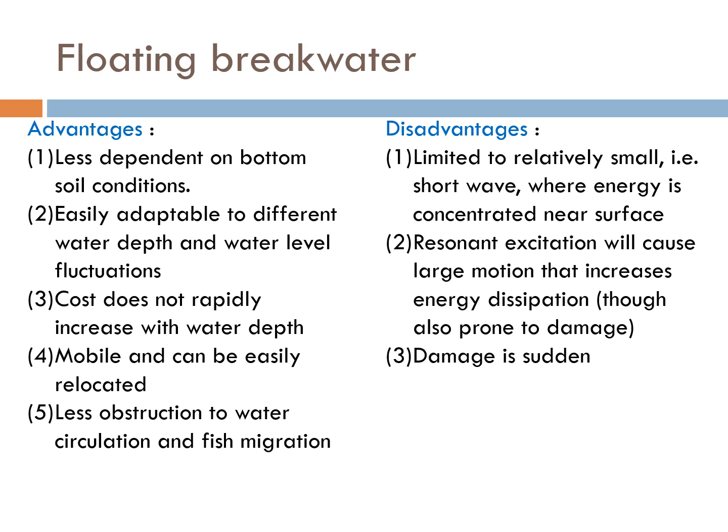Some of the disadvantages of floating breakwater is that it is only applicable to short waves, where the wave energy is concentrated near the surface. For long waves, such as tide or tsunami, where the wave energy occupies the entire water column, it will be able to pass through floating breakwater without being reflected or dissipated.